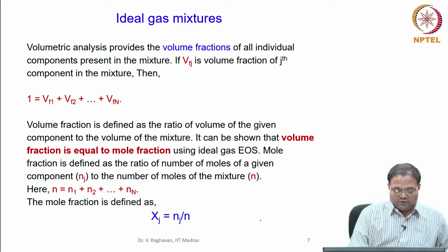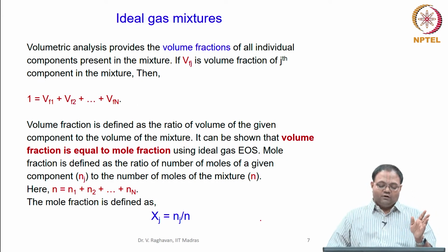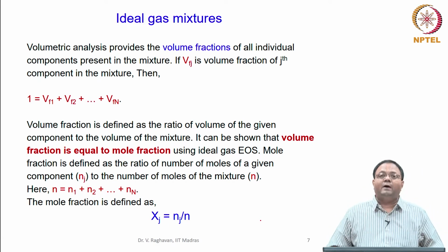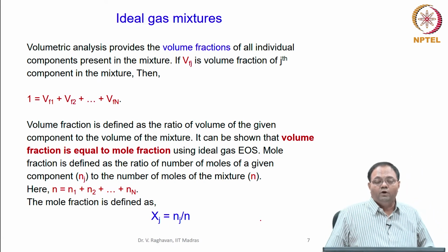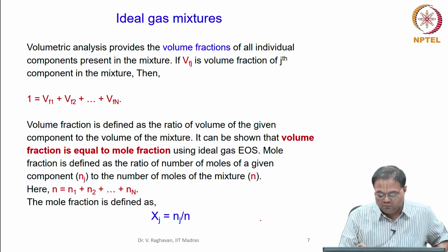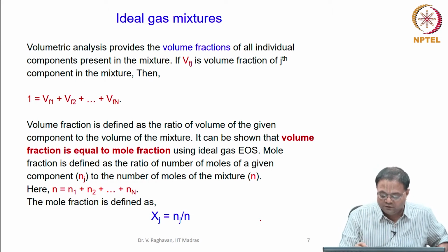So, you get the volume fraction. Now, volume fraction is equal to mole fraction. Actually, we can easily prove that by using Amagat's law of partial volumes. When you use that, we can prove that the volume fraction is nothing but the mole fraction. So, for example, we can write like this.